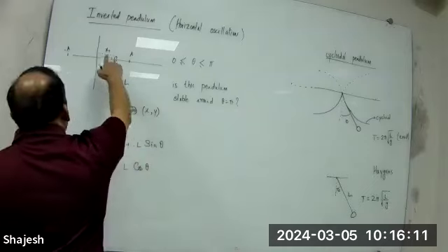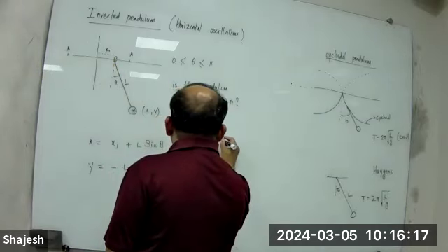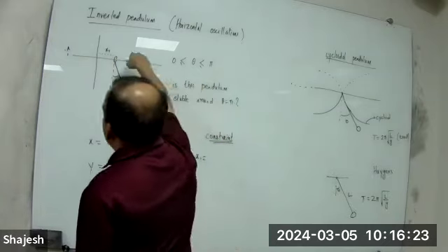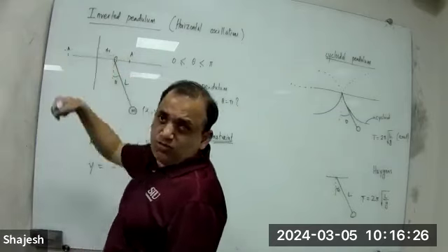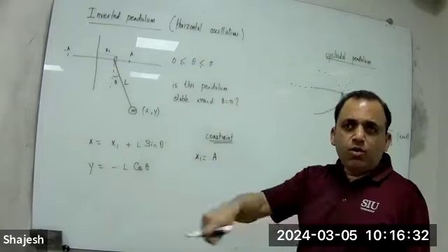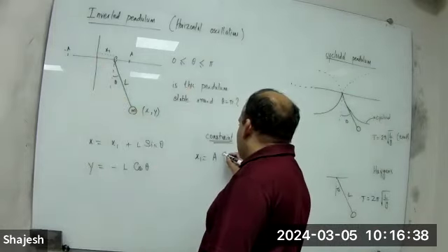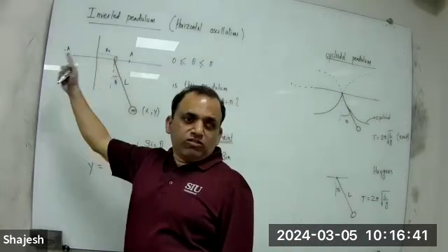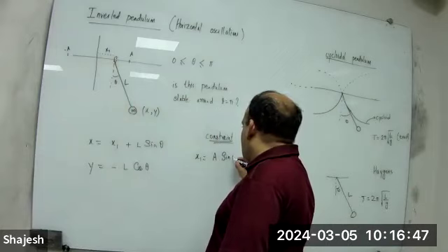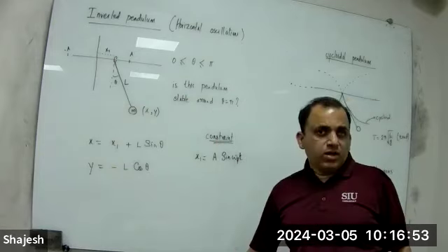We also have X1 given to us, so the idea here is that this is a constraint now. The constraint is that X1, I'm going to force it. I'm forcing this X1 with a simple harmonic motion. So A times sine, we can start with 0 maybe. There is some frequency it oscillates with. So let's say it is omega forced, because it is being forced. So X1 equals A sine omega_f t.